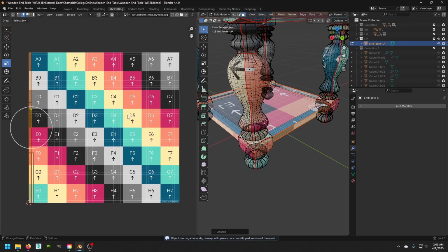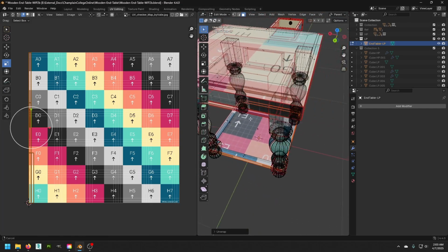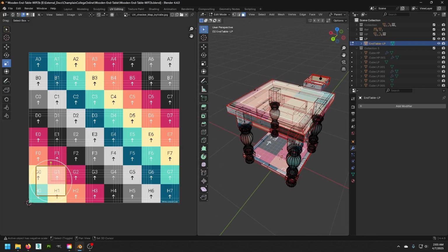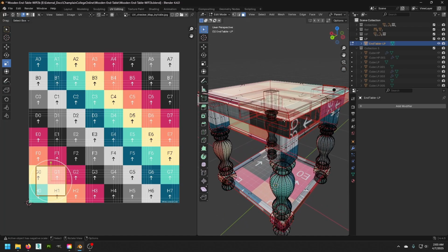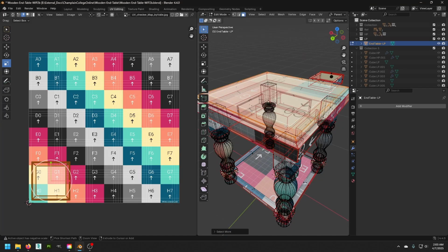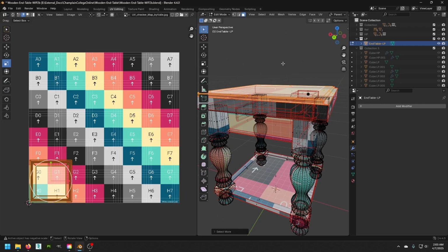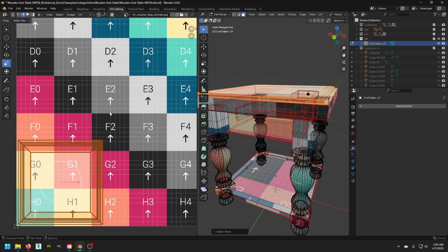None of those are quite what I want. I basically want a large strip like that. The only other one would be this one. Oh, how to grow a selection there: if I select the top one and press Control and the plus on the numpad, that will increase the selection.